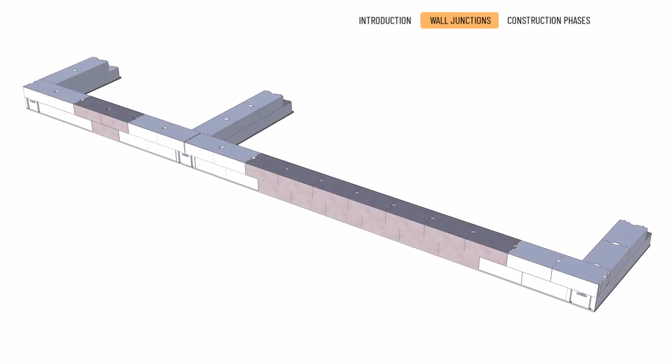Wall junctions. Using a sample wall, we will investigate the wall connections of 37.5 cm wide aerated concrete masonry block. The type of blocks used is a tongue and groove one with handles, which measures 37.5 by 60 by 20 centimeters. The allocation of blocks is planned as follows.